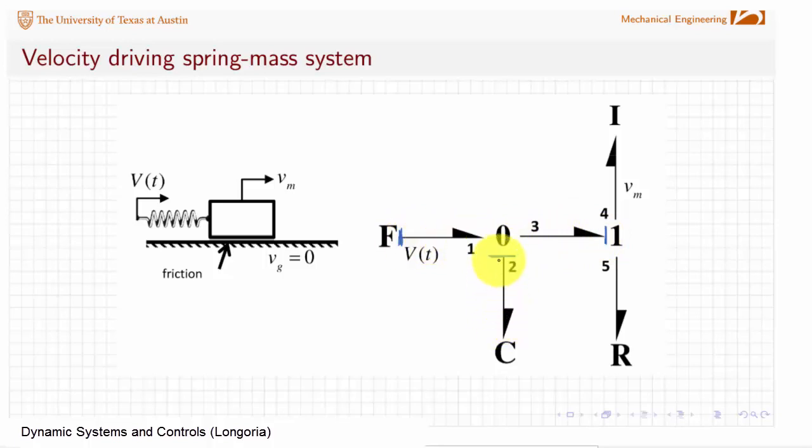Causality, flow, causality, effort. Power is telling you something totally different about the variables on these bonds. Focus on the causality. So now I've applied effort here. This bond is flow. This bond now is applying a flow here, but effort onto the 1. Since an effort on a 1 junction does not constrain any of the other bonds, I can now go to my other energy storage element and apply effort into the I element, which makes this also in integral causality.